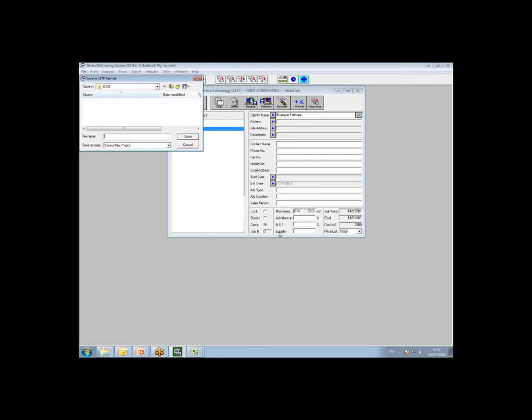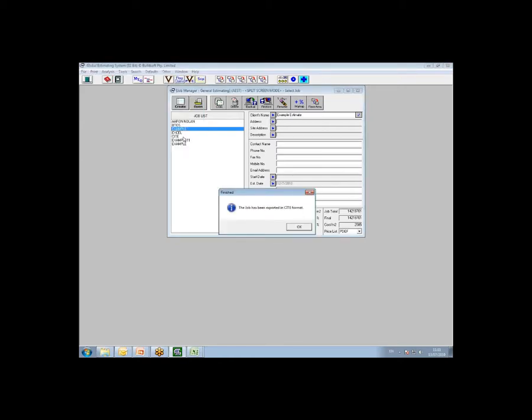If you hit yes on that, the next thing is it'll ask where you want to save this file and what you would like to call it. Again, you can choose wherever you'd like to. I'll just browse on to my C drive and put it in the webinars folder that I have been using. I have a site files export folder here, so I'll choose in there. I have no files in it at the moment. Then we just choose what to call it. Let's say we call it example, because that's the name of our job. Then all you have to do is hit save. Once it's finished, as you can see, it's quite quick. The job has been exported in a site format, and we just choose OK.